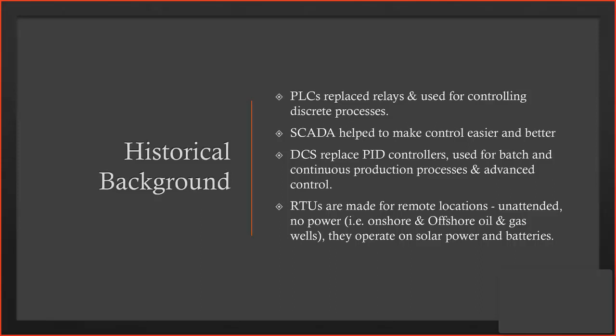So the idea came up: DCS. What is the DCS? DCS is actually a proprietary and turnkey solution. It has the SCADA part as well. It has the PLC part, but in a modified shape; it is not the same PLC. It has controllers, but with different features.